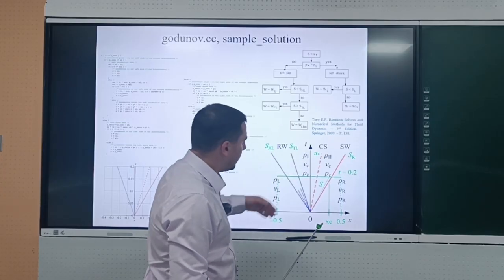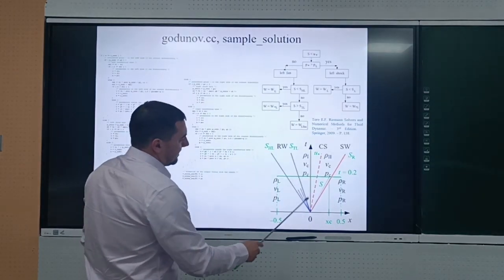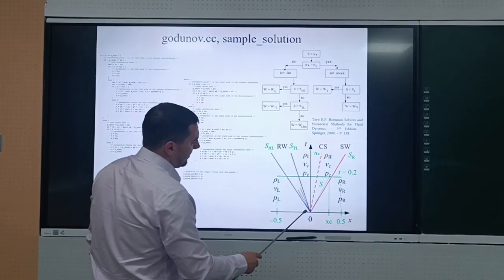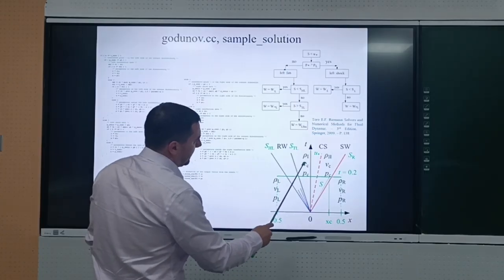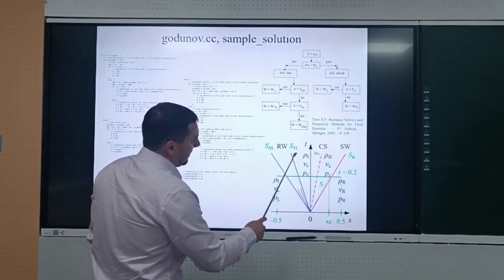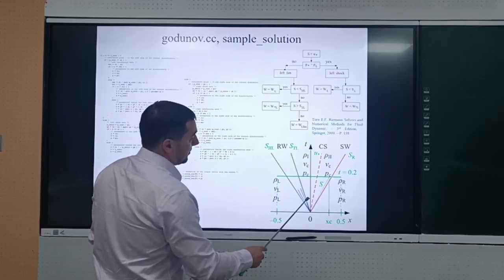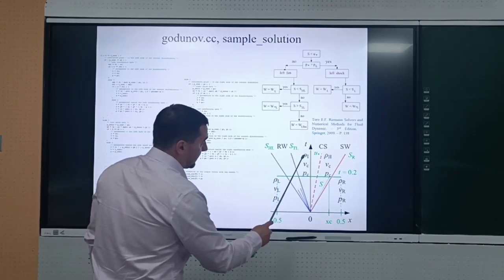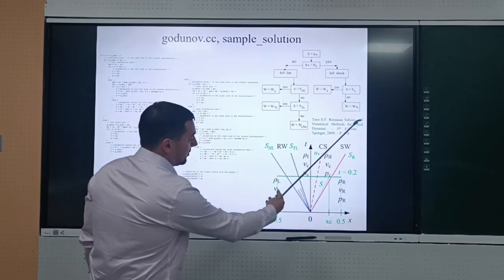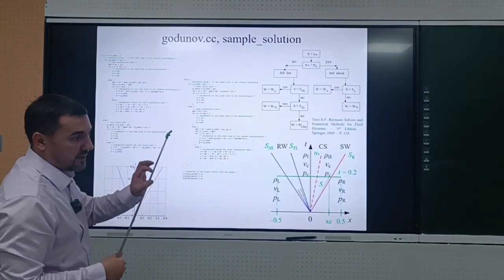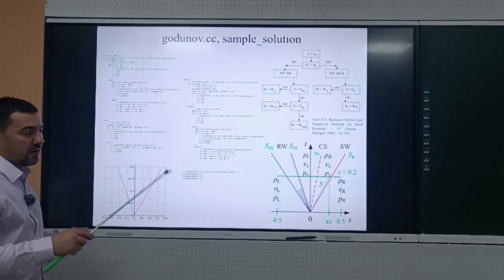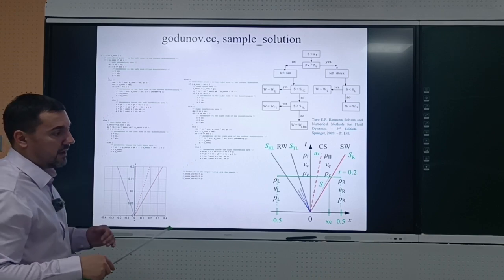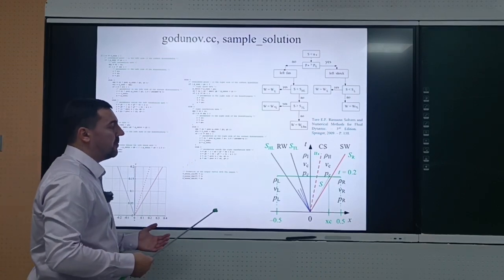For example, in this picture, the axis x equals 0 corresponds to the area between the contact discontinuity and refraction wave. It means that these parameters ρ1, Vc, Pc should be taken. We should take them and put them into the flux: ρ, ρv, ρe, and that's it. And that's the essence of the Godunov method.